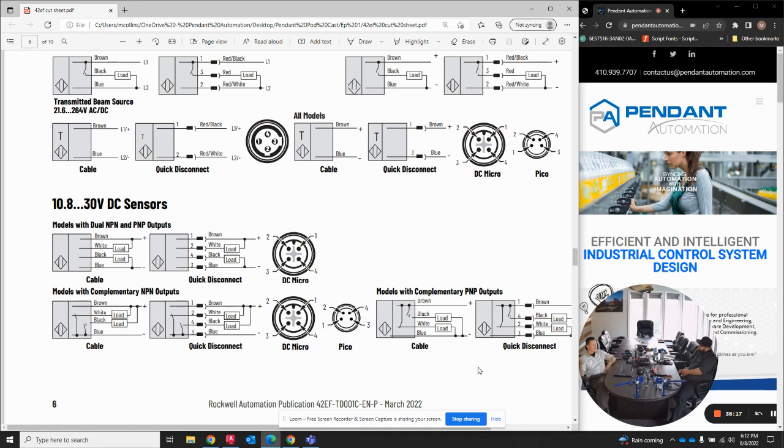Like when we get machines from Europe and they're done with Siemens, even though we've had TIA Portal since 2010 and it is awesome compared to the old Step 7 version 5 point whatever and before, they're still sending machines out in Step 7 software and they're still using the 300 processor, which I also heard is being phased out. It's actively being phased out right now, so you won't even be able to buy that. And so it would make sense that they still use NPN, because that was really the old school way of doing things.